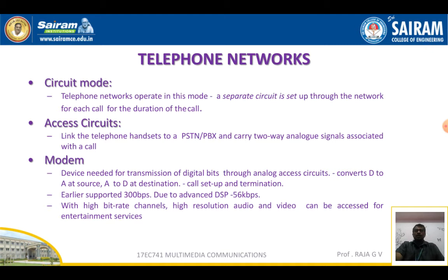So the modem at the sending side converts the digital output by the source digital devices into an analog signal compatible with the normal speech signal, which is routed through the network in the same way. At the receiving end, the modem converts the analog signal back again to the digital signal. So the necessary circuit is set up for the call termination and setup.